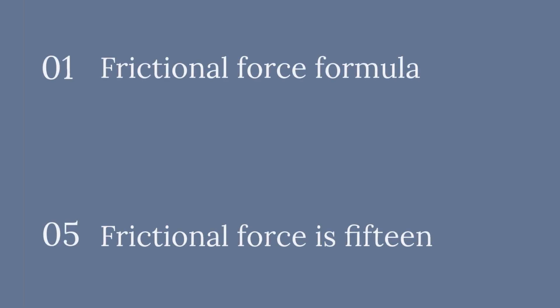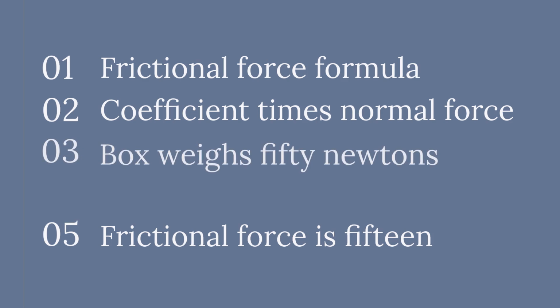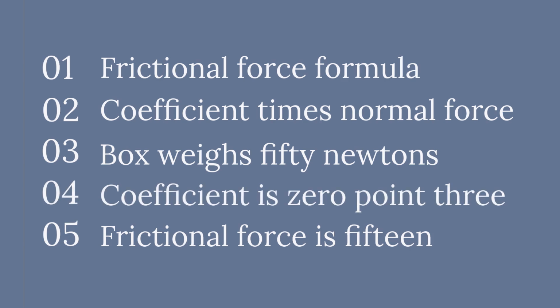Frictional force is calculated as coefficient of friction times normal force. For example, a box weighing 50 newtons on a surface with a coefficient of 0.3. The frictional force is 15 newtons. This calculation is essential for understanding motion resistance.